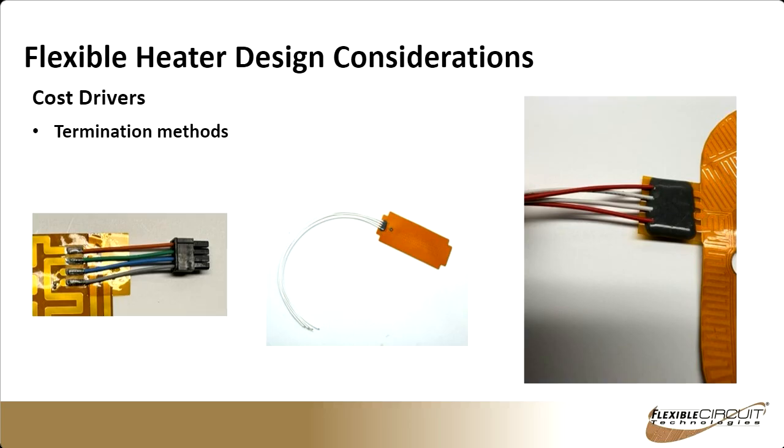Hey, Mark, hold on that slide for a second. So the image in the middle there has a little dot of epoxy to the right of the lead wires. There was a question that came through: what low height thermistor component would be suitable for flex heaters to avoid hand soldering? So typically, we put all kinds of components on both flex circuits and heaters that are pick and place, very, very small thermistors, readily available on DigiKey.